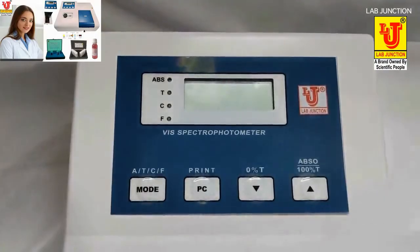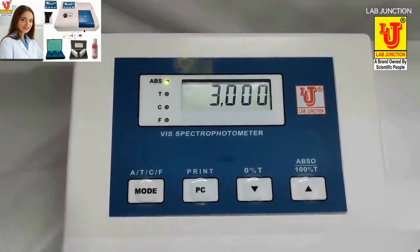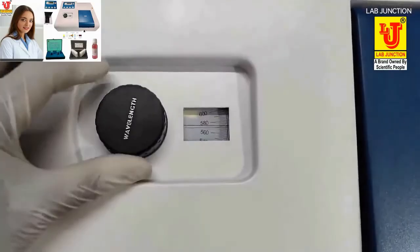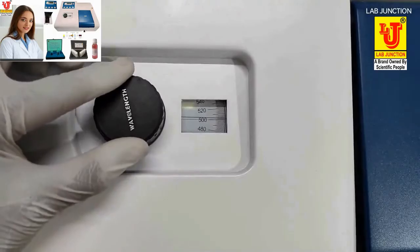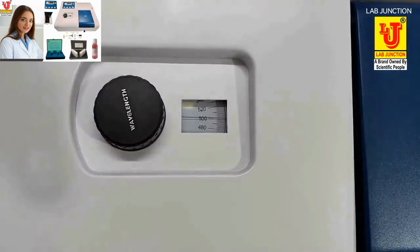Now I switch on the instrument from the back side control. Now first set your wavelength. I am setting 500 like this way. As per your application, you have to set your desired wavelength. My wavelength is now 500 nm.